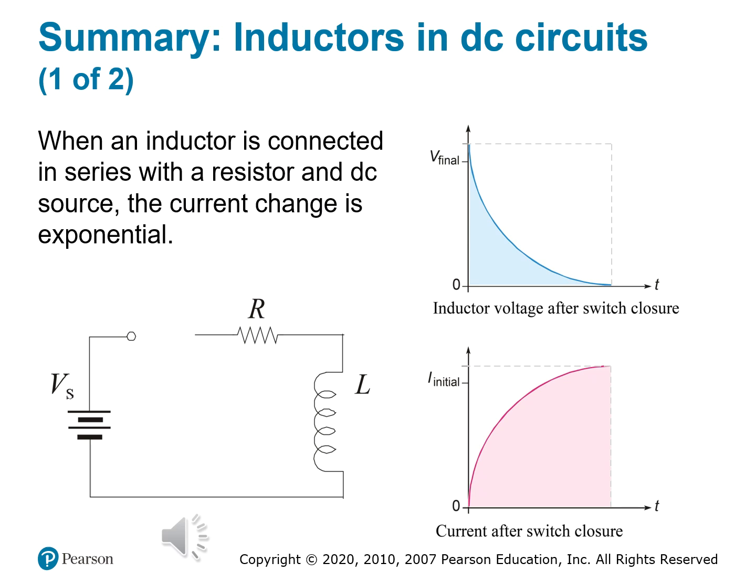So at T0, the inductor sees a sudden change. It generates an opposing voltage. The voltage across that inductor is maximum at the start, and then it decays to zero. The current starts at zero and then gradually increases until it stabilizes. And we see this in the graph there on the slide. The top graph shows voltage across the inductor dropping exponentially after the switch closes. The bottom graph shows current through the inductor increasing smoothly over time.